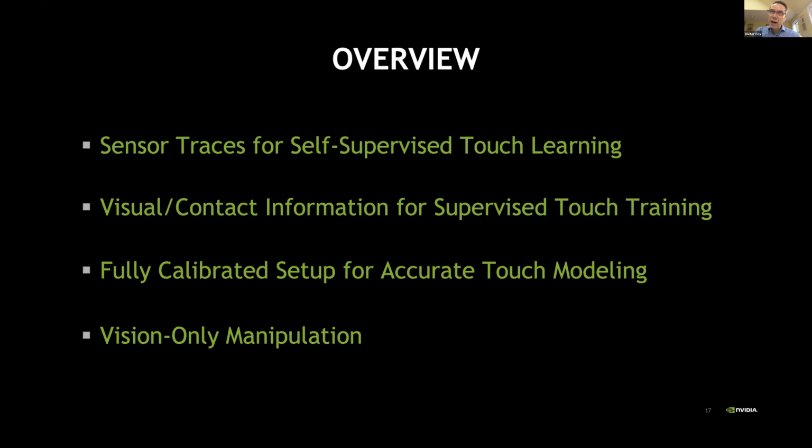Okay, so this was now going from almost unlabeled data to a more sophisticated labeling effort, where we're using visual tracking together with contact information in order to provide the supervised data that we need to learn the mapping from electrode measurements to forces actually being applied to the fingertip.